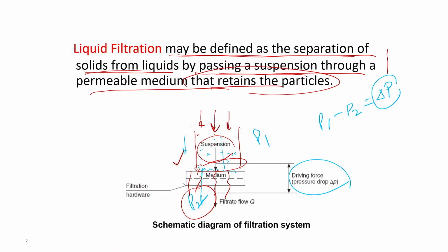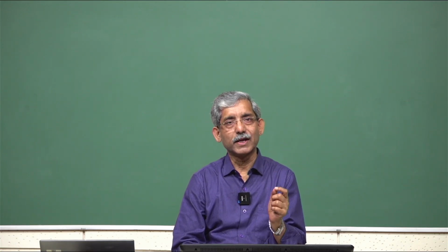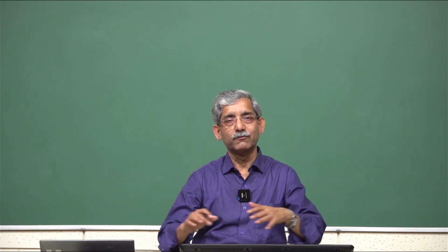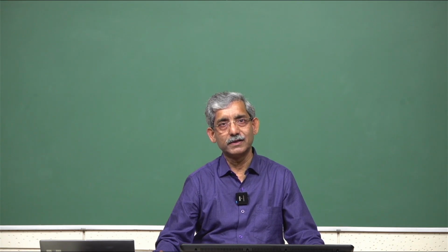Suppose in water, as we have discussed, it is actually a mixture of many large particles, small particles, virus, bacteria, salt. Suppose we do not want to restrict the salt from flowing through, and the dissolved salt has a very small diameter. So, we can select a filter or membrane with a pore size larger than that salt size. So, we can maintain selective restriction here.